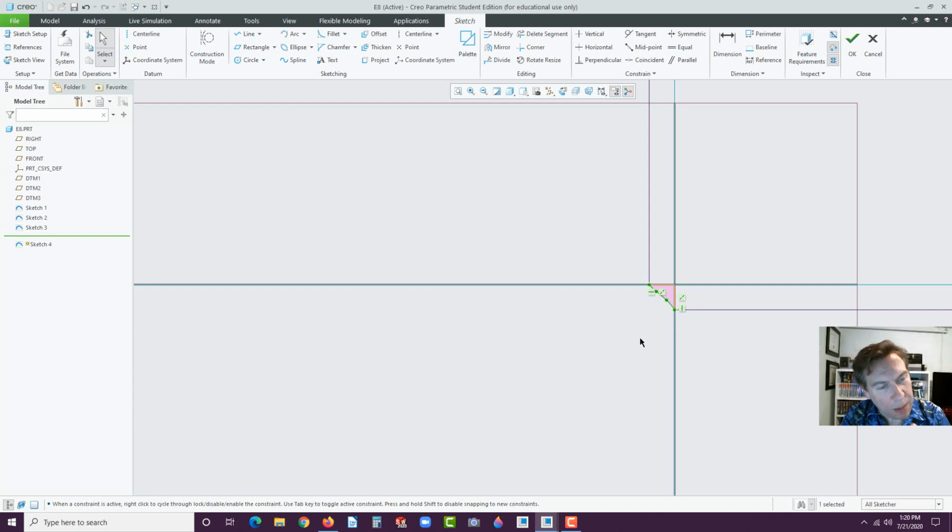Now, some might ask, why don't you put analytical geometry, like a line there? I've seen strange things happen when you go from a spline and then transition to analytical geometry, either arcs or lines. It starts to possibly have some issues. Might not in this one. I haven't tried it in years, but I wouldn't bother. There's no need to. Stick with splines.